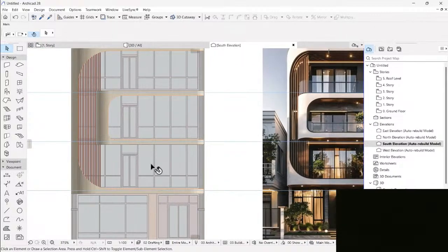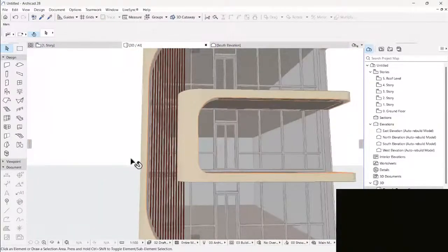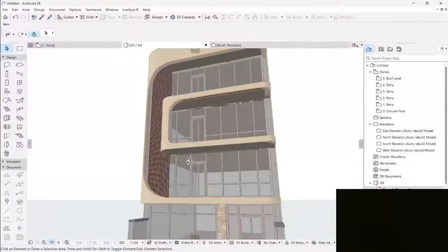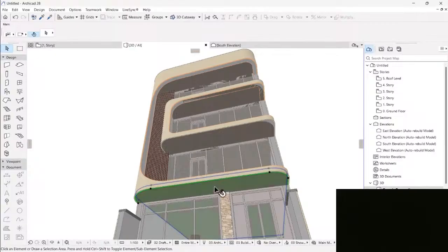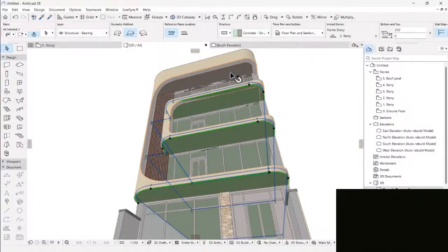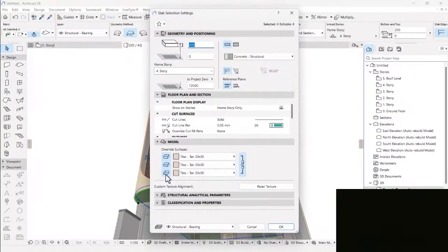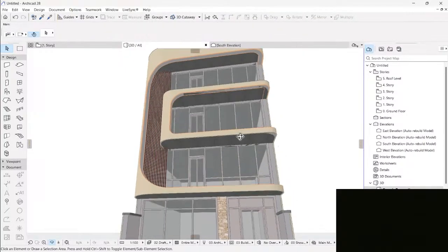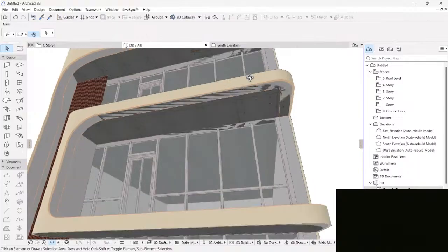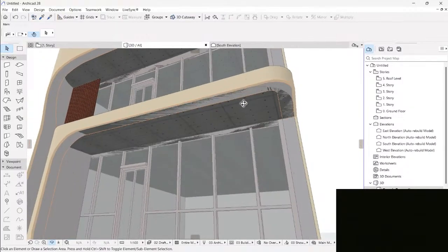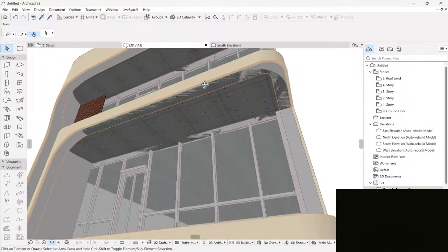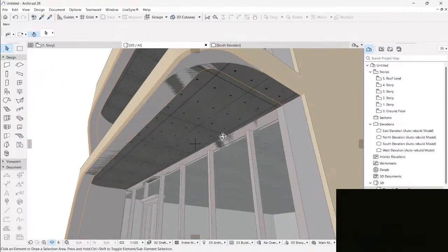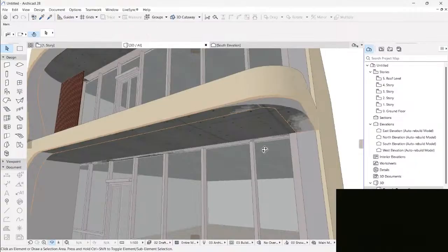Okay, so check on 3D. We now have that being placed. All right, so if you look at our slabs, they are tiled underneath, which is a wrong representation. So we need to uncheck the bottom one just to have concrete like that. Perfect. And then I don't know, we have this glitchy, I don't like it, the glitch of materials.